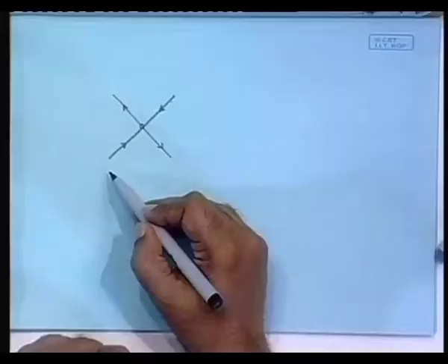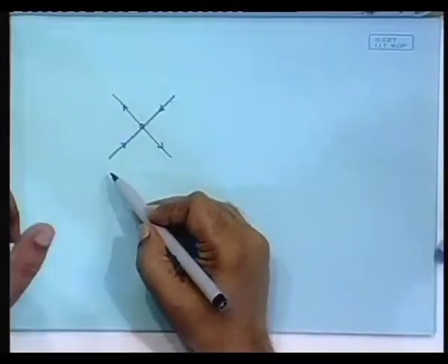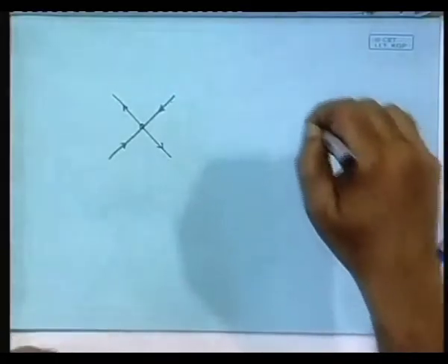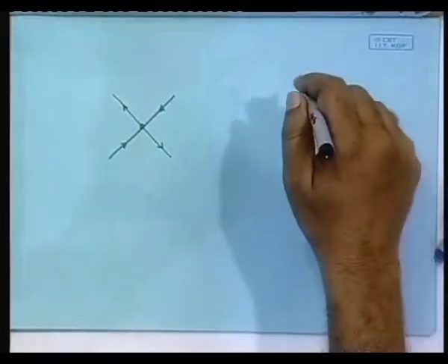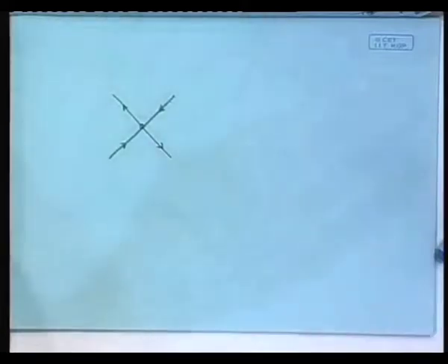Now, if you go out of the local linearized zone, where the local linearization is no longer valid, then obviously these lines will no longer remain straight lines, but still you can identify the lines which have that property that if you start from a point on that line, it will forever remain on that line. We have gone by that argument in the continuous time systems also. The same thing will be applicable here.